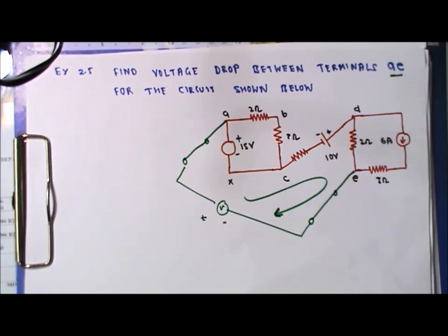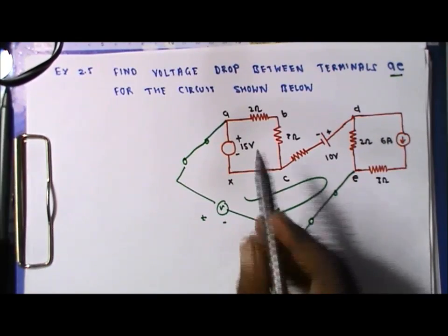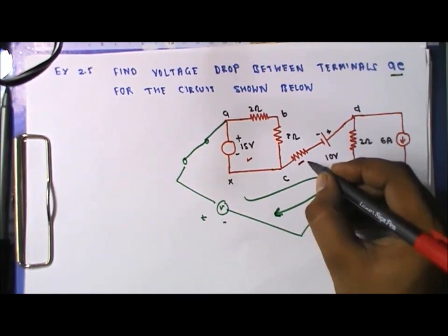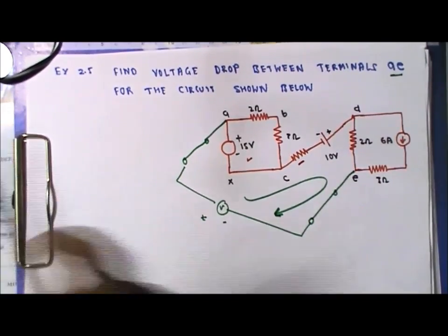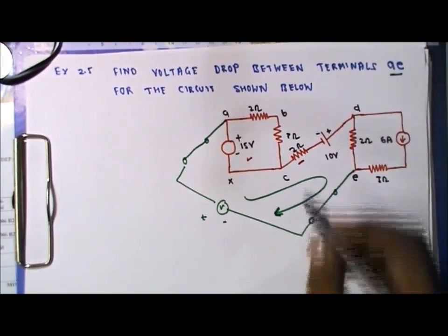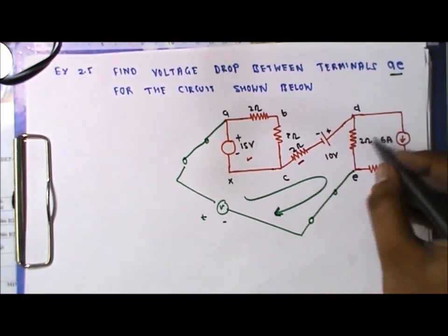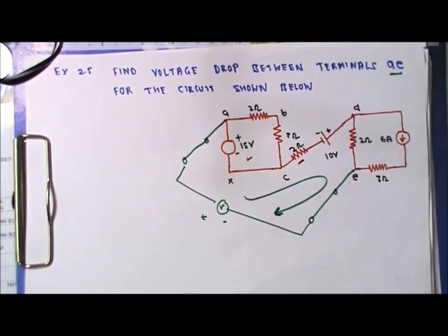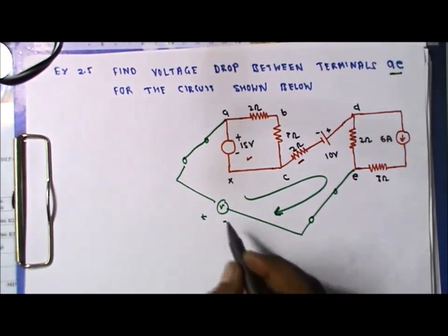So first we have to calculate this drop. This is the voltage source. If we are able to calculate this current which is flowing in this resistance, let us suppose this having a value of 2 ohm, then we can solve these circuits and the current which is flowing in this 2 ohm resistance. So what the procedure is that it is open circuit.